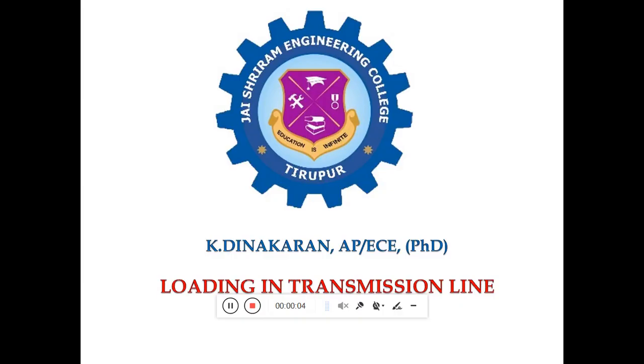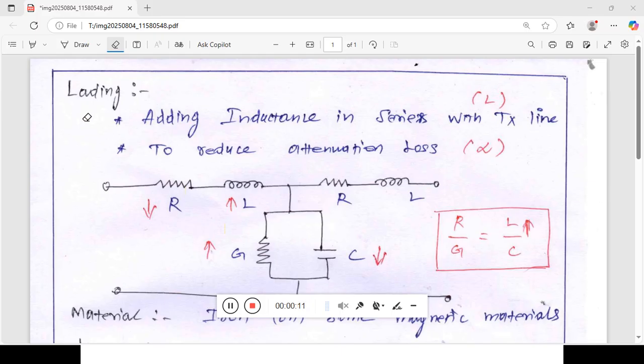Today's class, we are going to discuss loading in a transmission line. Here, we are going to discuss what loading is and what the types of loading are. First, what is loading? Loading is nothing but adding inductance in series with the transmission line, which means we can increase the inductance value over the transmission line.